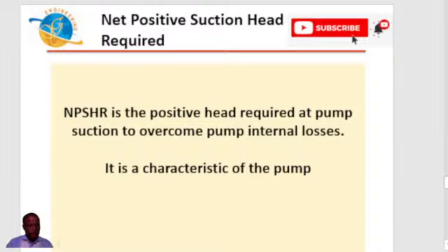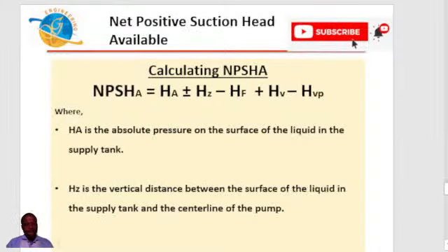Now let's continue. The question now is, how do you calculate NPSHA? Because I mentioned to you that your NPSHA is a characteristic of your system.